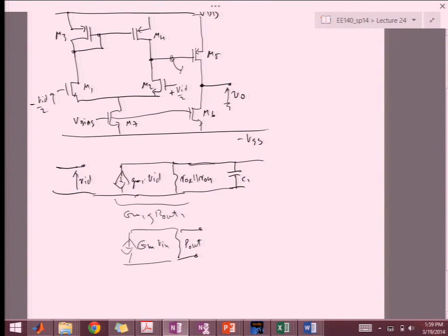And then I can add here a capacitor C. That's originally from CGD, but I would like to add a capacitor there, like we talked about with Miller compensation, which we did for bipolars, in order to see what the effect of this is on poles in the circuit. And then I have C2 from the output. And then, of course, from M5, there is GM5.